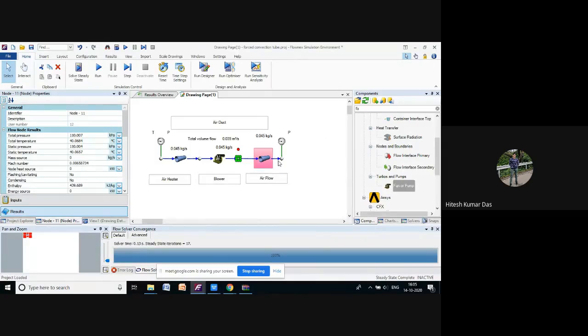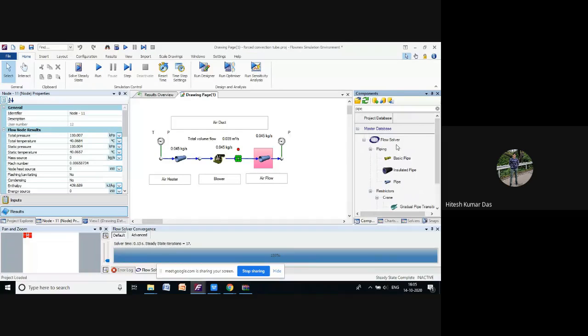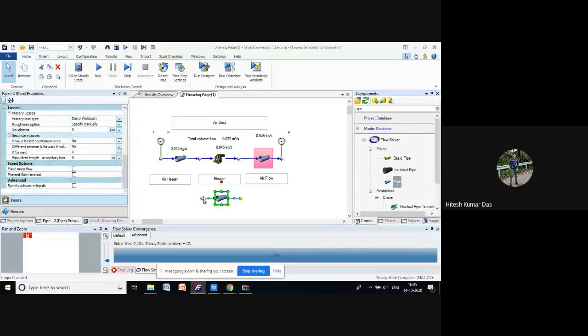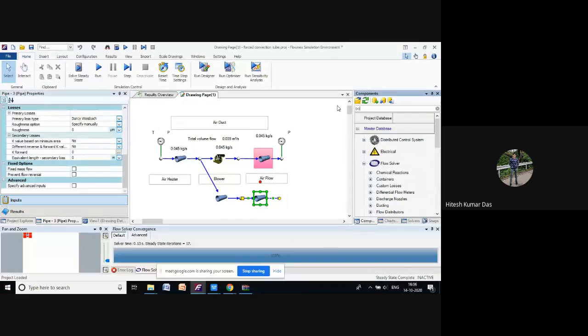Like this, one flow is happening. If you go for another branch, we introduce a pipe in another part. Just click on it, add an upstream node, and for this, click another pipe and mention one boundary condition. It's very easy. Yes, you can do that.